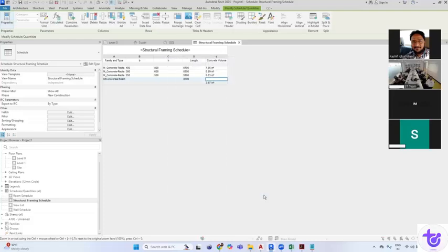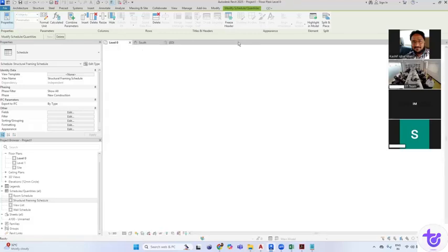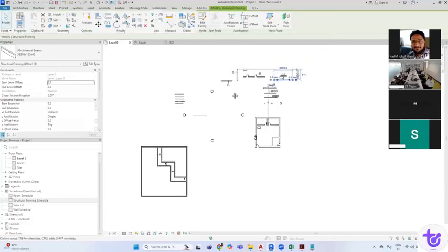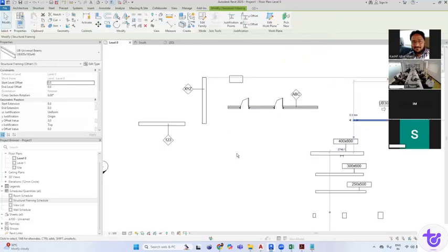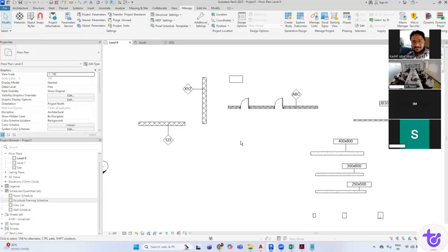So try to do some exercise for the shared parameters, for the project parameters, for the global parameters. Also, project parameters are essential to be practiced, because we should know what is the difference between the family parameter and the project parameter, how it is applicable to different categories, how it is differentiated from the family parameter. It is always good.